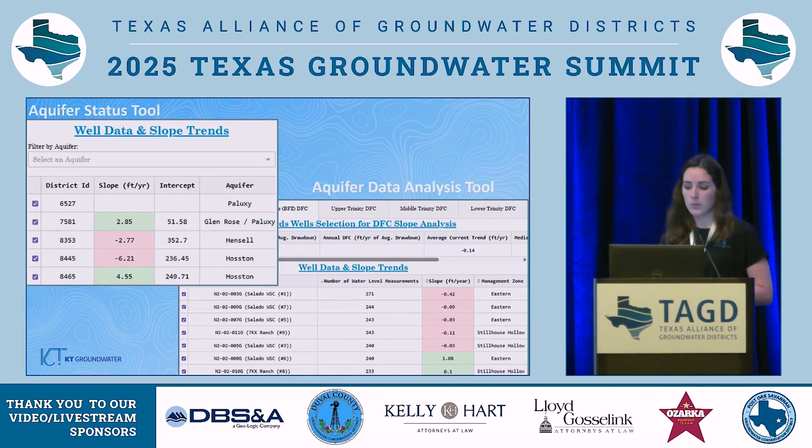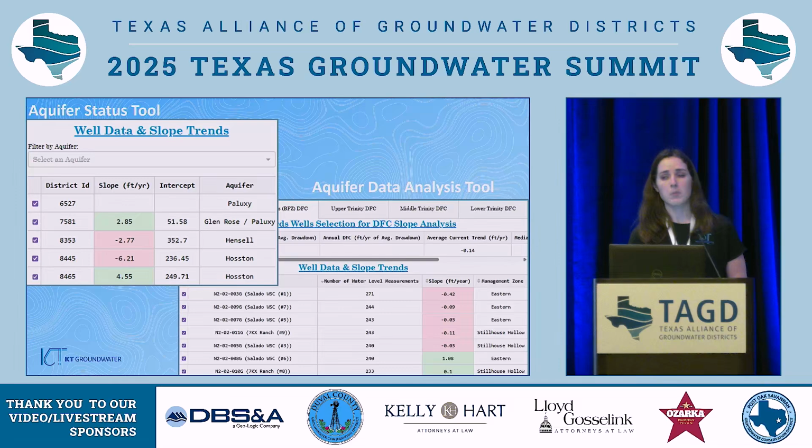These tools also display water level trends for each individual well, and these tables can be filtered by aquifer. The checkboxes on the left side allow you to turn off a well so it's not included in the overall trend calculations. This gives the user the ability to introduce nuance and their best judgment if something doesn't look right, or if they know a particular well has inaccurate measurements.